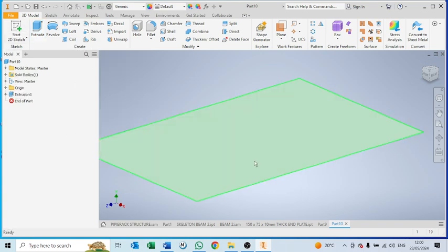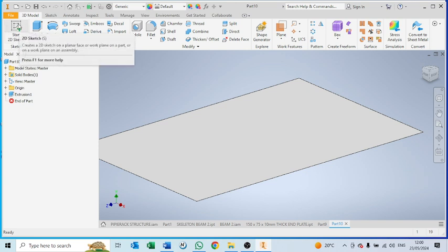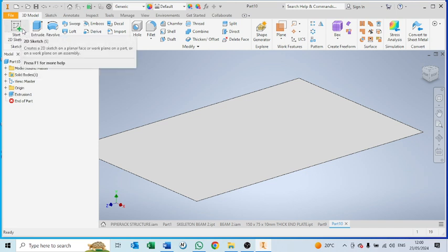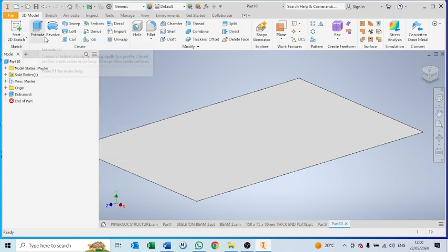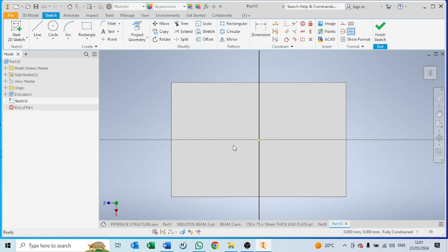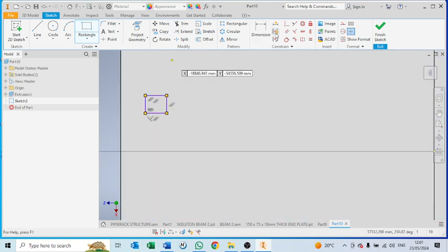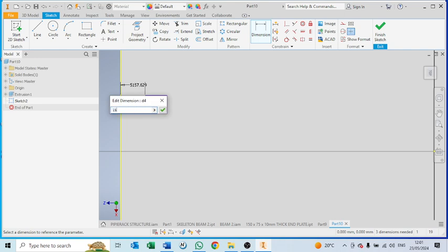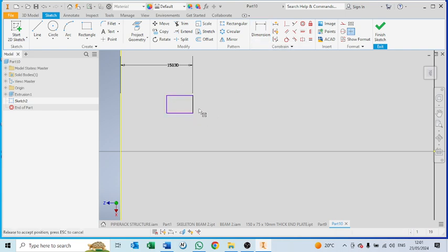Okay. Then on top of it, I need to put the layout of how I want the pipe rack to be. So I'll create the print where the pipe rack is going to sit. So I want a cross this time. I'll just make a cross. I'll draw a print there. Then from the edge, I'll dimension. This time I'll say 15 millimeters or 15 meters. Okay. And because 15 meters, then I'll just drag that and say equal.